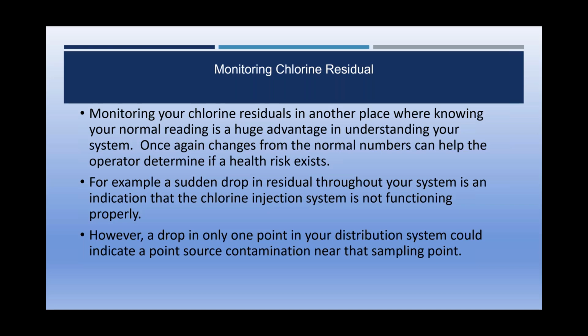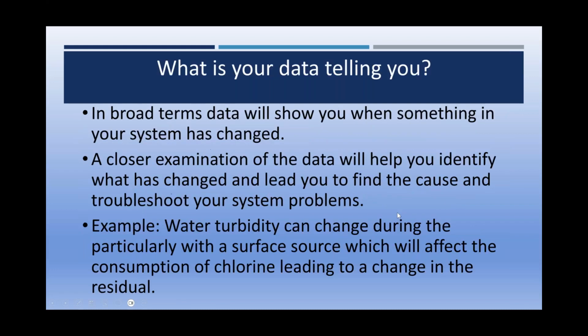We took a very close look at the house that the lead showed up in and realized it was an old water heater that they had that was somehow leaking lead, probably from issues with the solder in those old systems. So again, because you know your system's good, when you find an indication of lead, you can isolate it and go, okay, this is not a distribution system issue, this is a house issue.